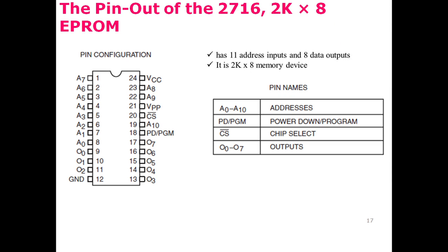It's a simple example where we have a chip 2716. The pinout of this chip is given here. The total capacity of this chip is 2 kilo cross 8. That means it's an EPROM, erasable programmable read-only memory. So the data can be read from this chip, and the organization of this memory is 2 kilo, that means that 2 kilo are the locations. So you would need 11 pins in total, designated as A0 till A10. So these are the address pins, and it has some control signals.